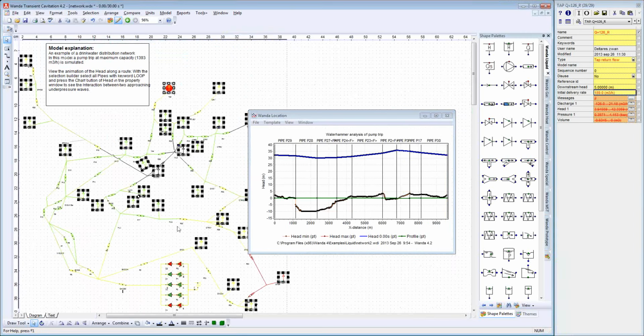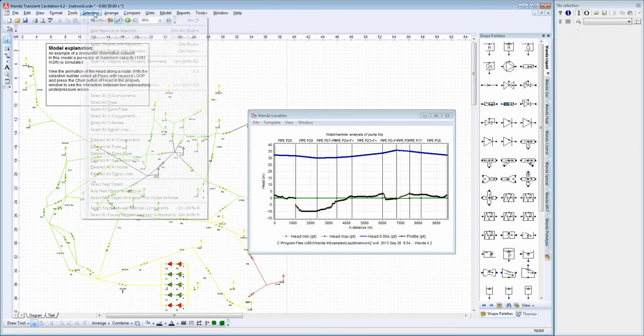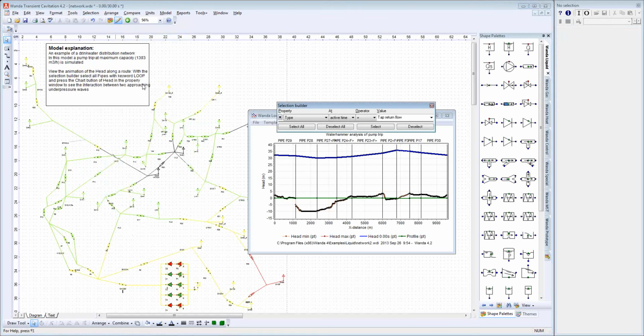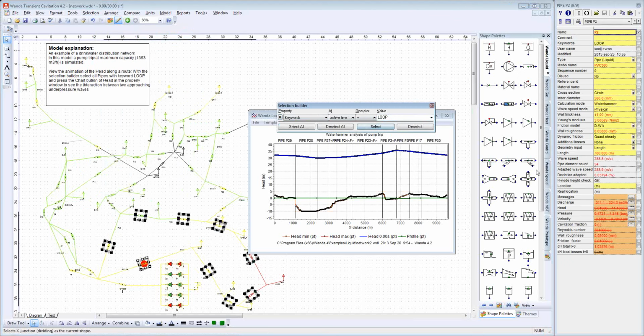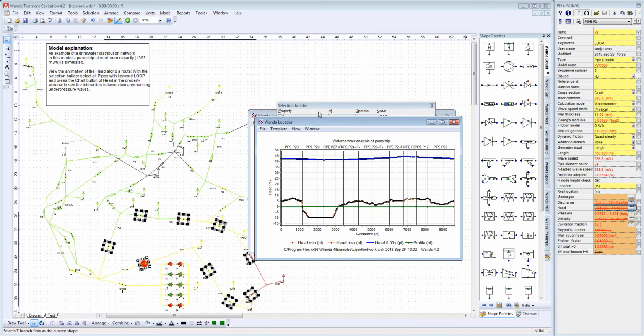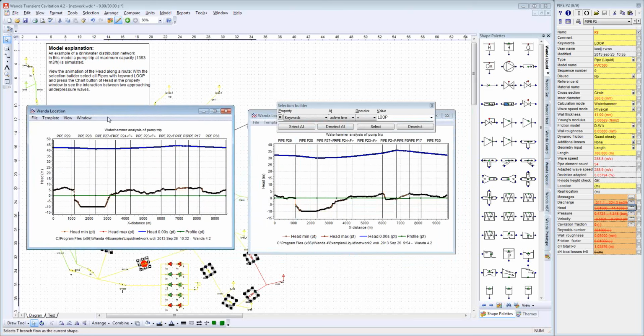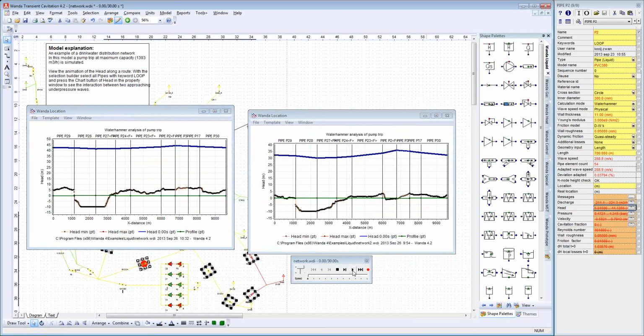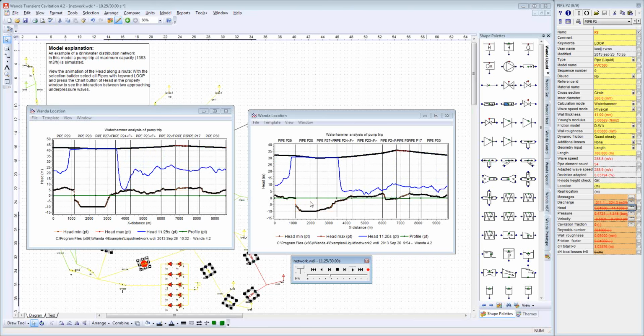And if I do it together with this other case, then press Ctrl T to get the Time Navigator, closing this one. You see it's plotting in both. You can easily compare the results from both. And this is the one with the higher flow rate, and then you see the pressure is a little bit less than in this case.